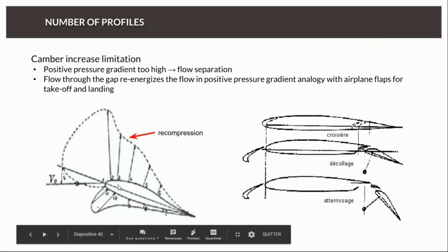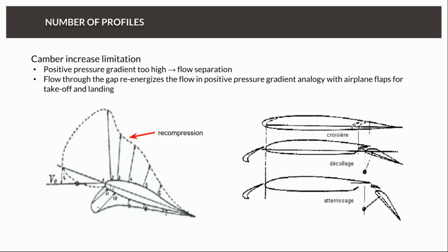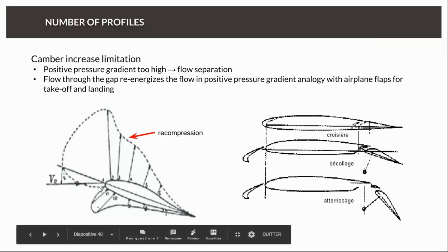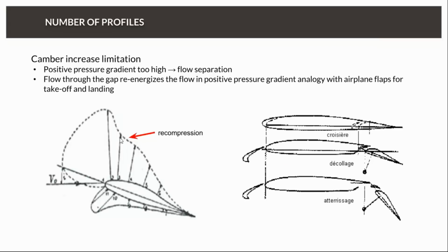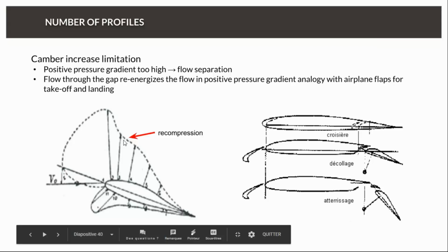If we look at the airplane, when I start to have a profile that's not symmetrical and at incidence, due to the overspeed on one side compared to the other, I get suction, and when I get suction, I also get at some stage recompression. And as we said, these are the main pressure effects created on the profile, so in this case I create lift on this profile.